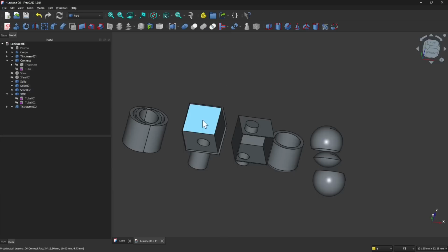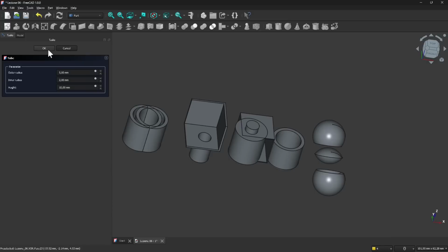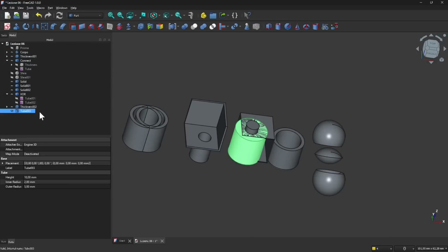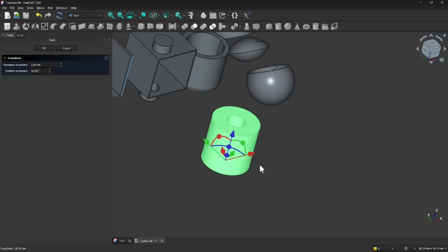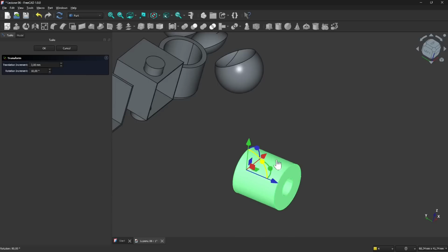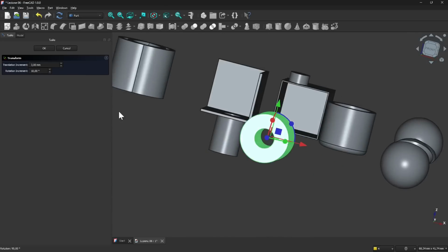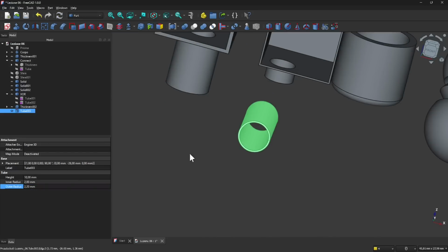So let's say that I'm going to add again, you can also find a tube here. So if you want, the tube shape will already contain a hole inside. So if I show it like this, you can see it has a hole, and I want to rotate this like 90 degrees. Okay, and say okay. And now I want to change the inner radius and the outer radius. So I'm going to say the outer radius is going to be 2.2, so really thin like this, or maybe a little bit more like 2.4.